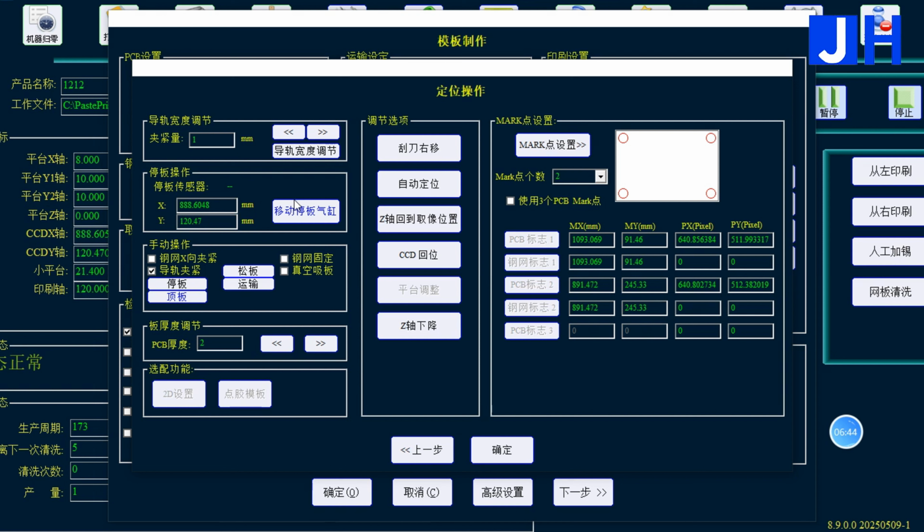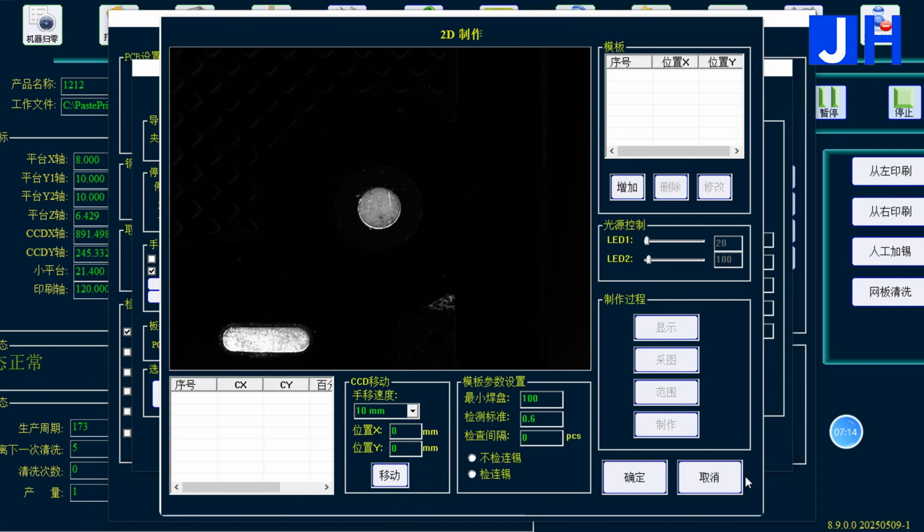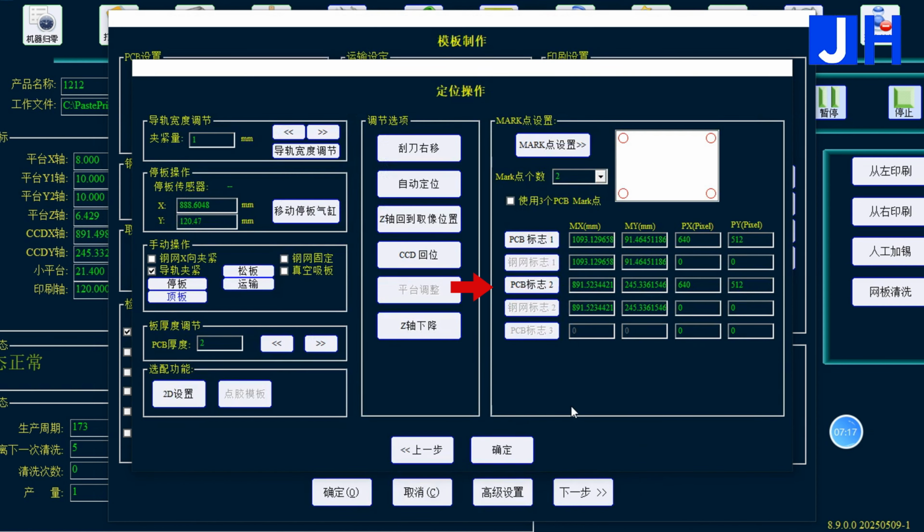This type of PCB structure is generally used for profiled shapes, and it is necessary to modify the position where the PCB stops during transportation. This is a 2D solder detection function, which mainly detects problems such as missed printing, hole plugging, and less soldering applications. This part has been introduced before, so I won't repeat the explanation.